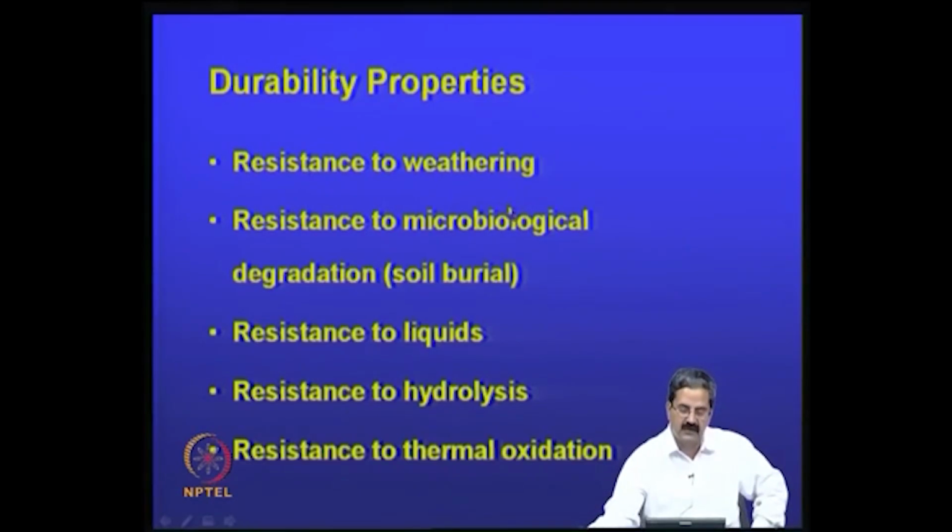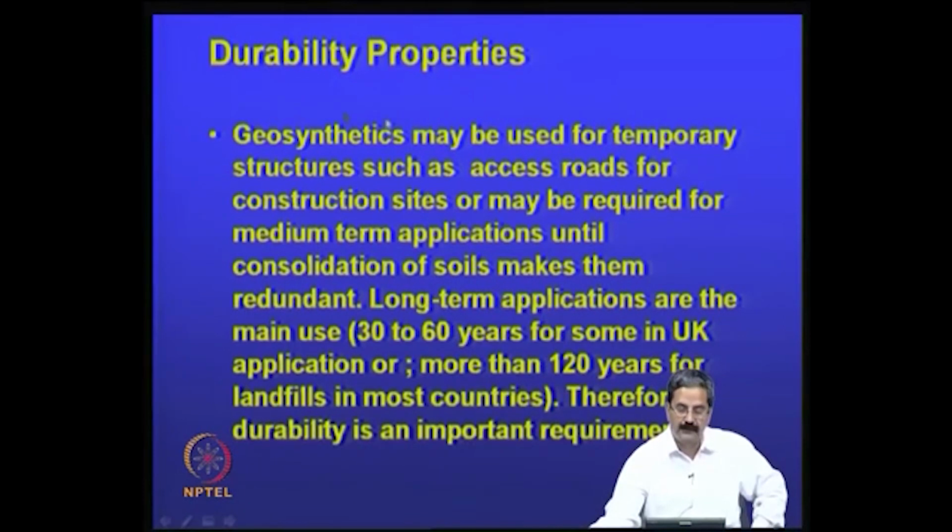So, you need to see resistance to weathering, resistance to microbial degradation, resistance to liquids, resistance to hydrolysis, resistance to thermal oxidation. Okay. Actually, geosynthetics may be used for temporary structures such as access roads for construction sites, or may be required for medium term applications until consolidation of soils takes place and they become redundant. Long term applications are also used, like 30 to 60 years and 120 years also. So, we have to see whether the material we are taking is good for short term, medium or long term. One should be very clear on this, then you can use it. So, you can find out its corresponding property and do that.